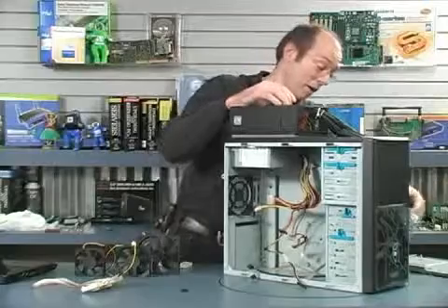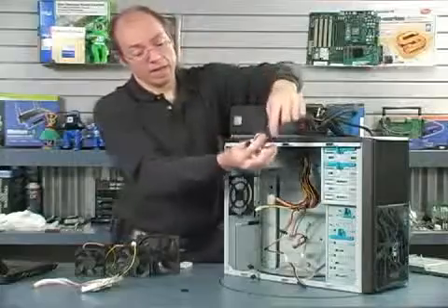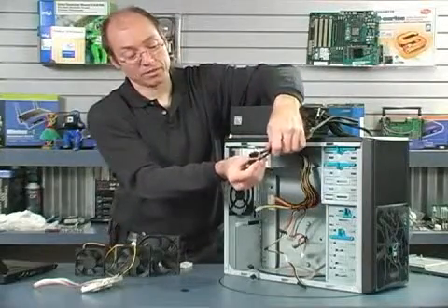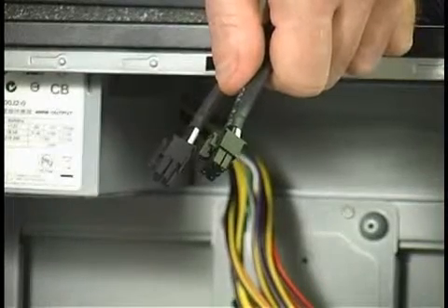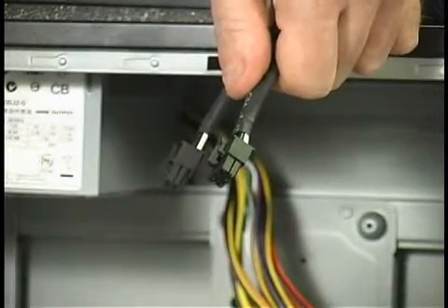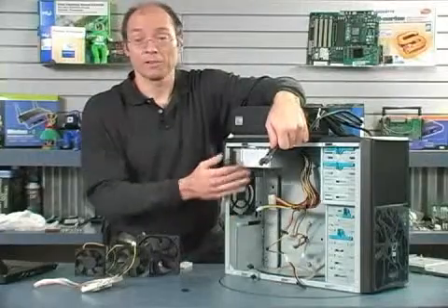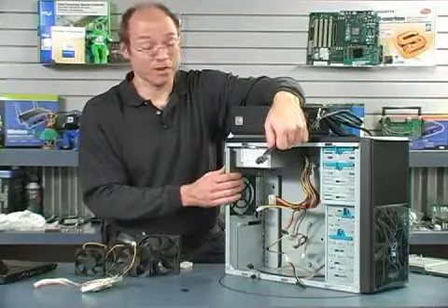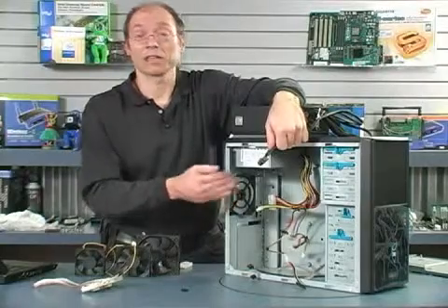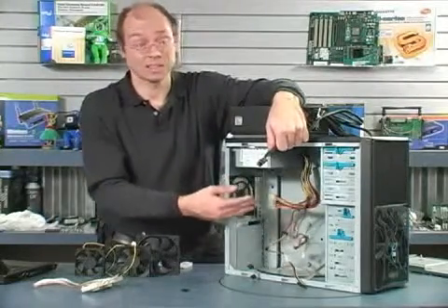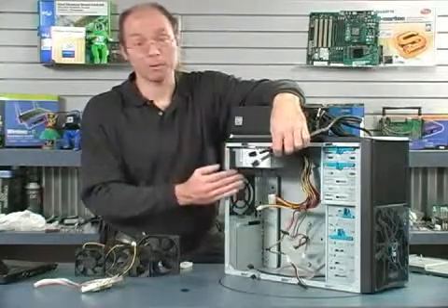Now another thing to look for is many video cards require their own power, and those come in the form of a 6-pin power connector. So this has what is called 2 PCI Express video power connectors, so I can run 2 high-powered video cards. If I was going to do an SLI with 2 video cards running simultaneously, this would be able to power that. So in fact, video cards can be one of the most power-hungry devices in the system. There are some video cards that consume more power than entire motherboards and processors do. So keep that in mind if you need a higher output power supply.